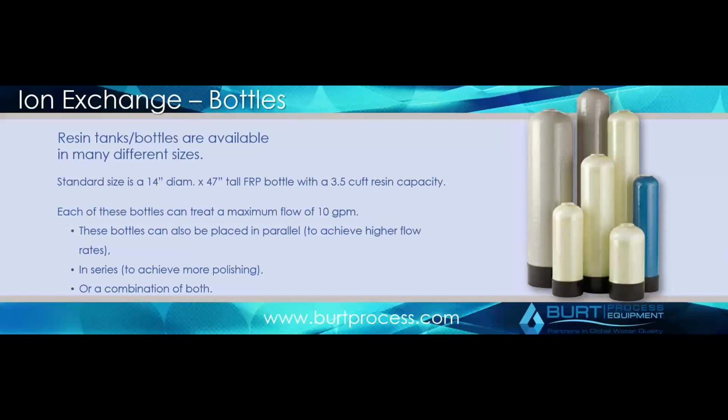The downside of traditional chemical resin is it has an exhaustion. You have a bottle full of these resin beads, and over time you'll have what's called exhaustion. You will have exchanged all of the cationic and anionic sites within the resin, and thus you'll end up having to replace your bottles at that point. So that's the downside, and replacing that resin is obviously a cost.